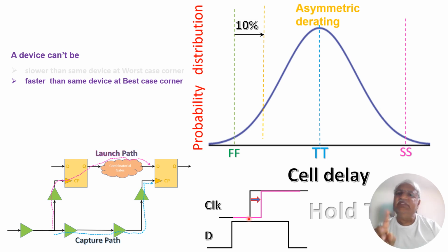Now if you observe, this is the asymmetric derate. That means the derate, whatever 10% or here 8% value, is applied to one portion of the timing path, either to the launch path or to the capture path. This is not the idealistic scenario, because there can be different timing path scenarios wherein this asymmetric derating may not be representing the real scenario in the silicon.